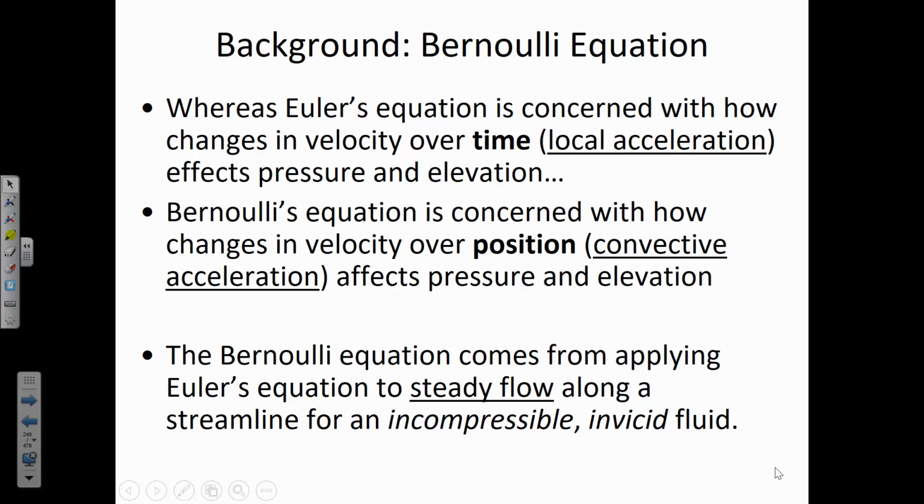There's no way that we can compress water inside of this control volume. Water is relatively incompressible, so what goes in has to come out. Now, it doesn't have to come out at the same velocity, though, and that's how we make it work. If the flow area is decreasing, then the velocity goes up. So here we have convective acceleration.